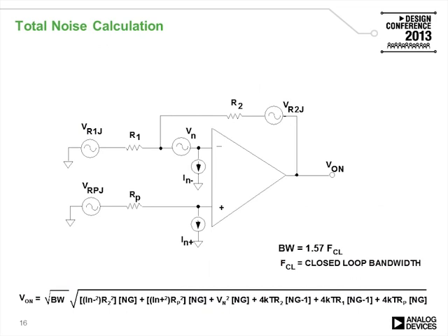The total noise calculation is shown on the slide at the bottom. So you can see that all the noise factors here in the amplifier are multiplied by gain, by the noise gain. And some of the resistor contributions are multiplied by the noise gain minus 1.